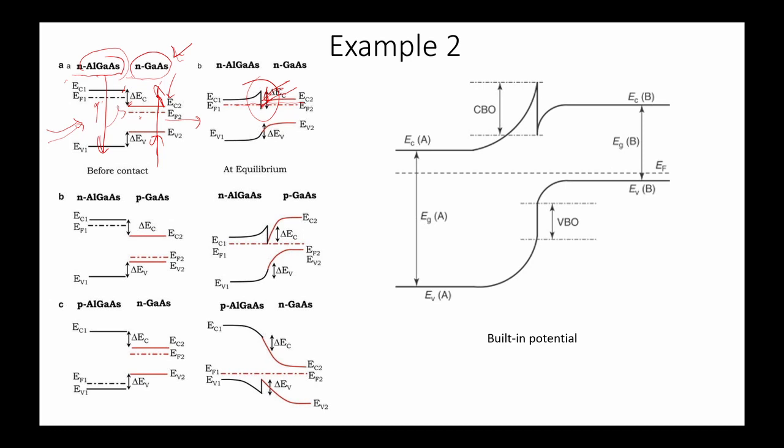So these types of devices can work at lower temperatures, and they will work better at lower temperatures, because there won't be any freeze out in this case. Freeze out happens in silicon, where there is no electron gas and the bands do not bend like this. So in this case there will be very good conduction, and the mobility will be higher at lower temperatures.